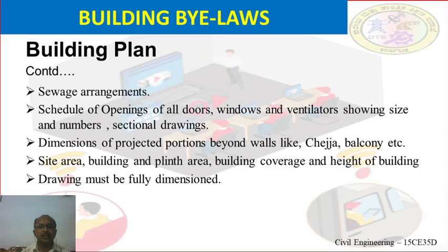You have to compulsorily indicate in the building plan the openings of all the doors, that means how many doors there are, for example D1, D2 and D3, and the standard dimensions of the D1 doors, which shall be indicated using the index on the right side top corner. And the number of windows shall be indicated by W1 and W2, etc.